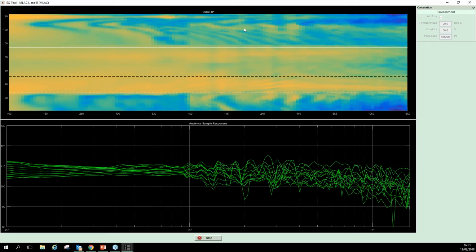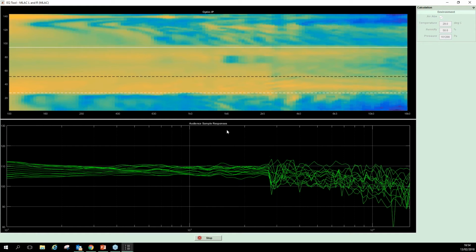And as you can see in the index plot above, the hard avoid area, which we will see and elaborate on in the next tab in our SPL evaluation, is quite cool across nearly the whole frequency band and is improving as our optimization works its way through the audible frequency spectrum. And our audience area is also becoming more and more even in terms of response. And our non-audience area on the ceiling is being optimized as well. So this is optimizing the entire room. It's just showing us the frequency response of our audience area, as you can see from the title of the graph there.